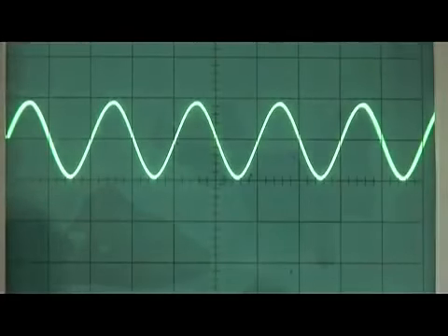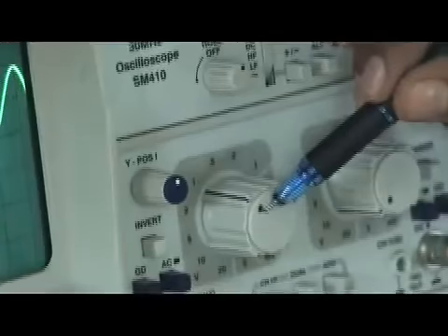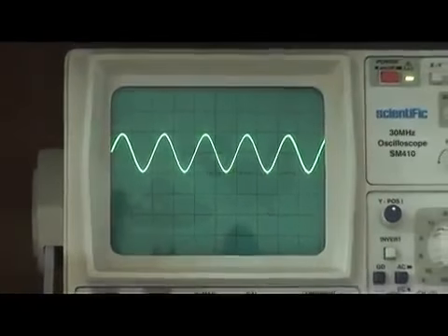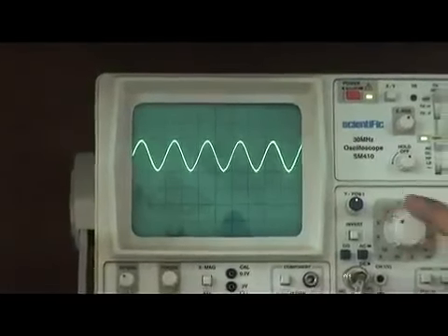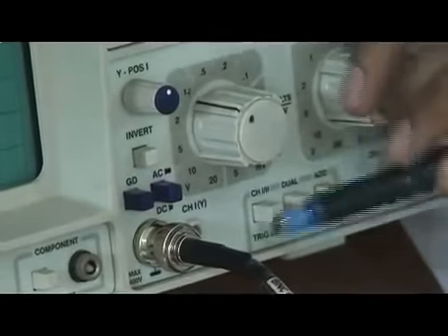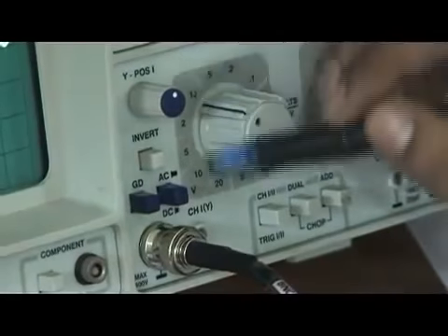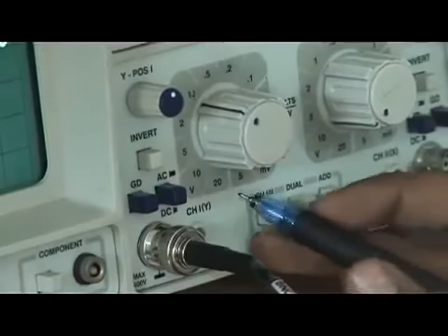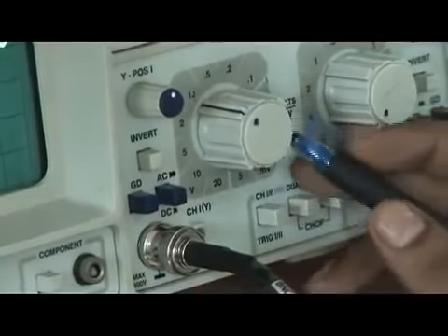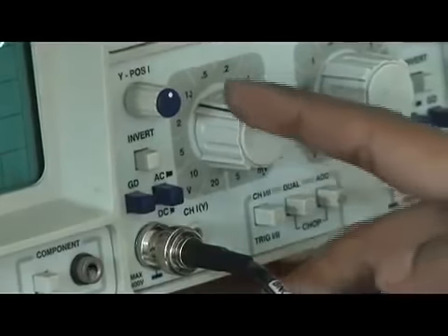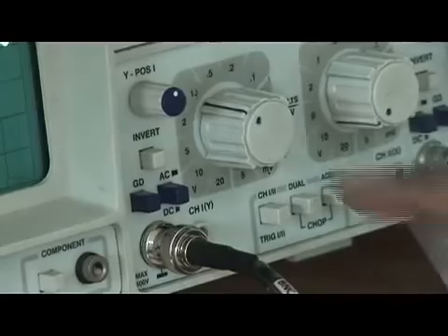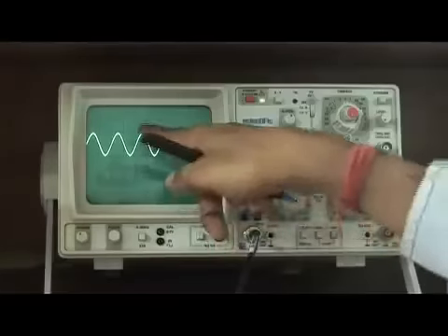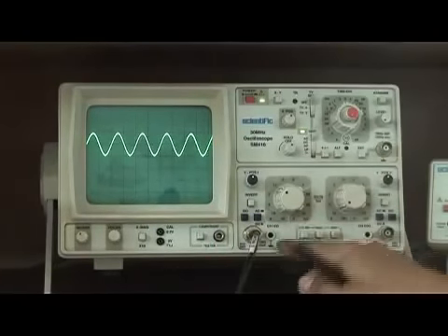That 1.9 into, you can see here where this knob lies, it lies at 1. So 1.9 into 1 is how much? 1.9. And what will be the unit? The unit depends on where this range lies. From this gap to this gap, there is no other unit except some numerical values. There is only one unit called V, meaning volts. From this gap to this gap, there are various numerical values, but there is one unit called millivolts. So whenever this knob lies in this range, the unit will be millivolt. When this knob lies in this range, the unit will be volts. So you are getting 1.9 blocks into 1, that is 1.9 volts.